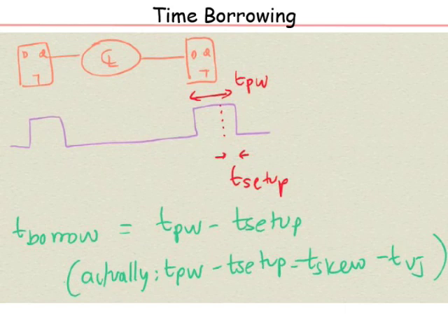If it is not okay, if you push that, then again you have a problem. Of course, you can push that and borrow from its following pipe stage and so on. So you can have multi-stage borrowing, and eventually it might work out okay. So analyzing time borrowing can happen across multiple stages, and analysis of that can become quite complex.